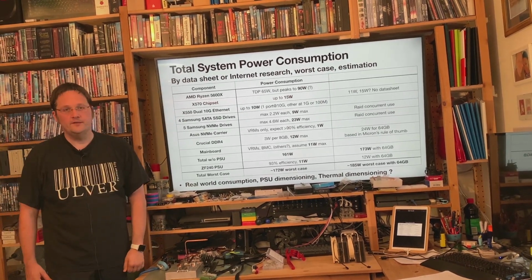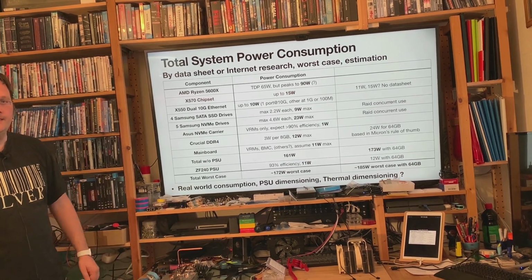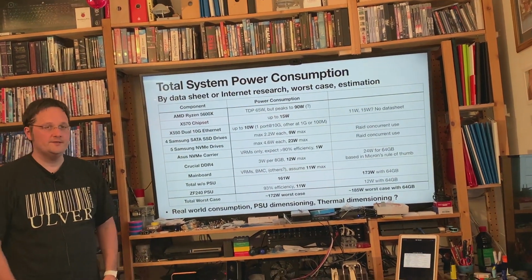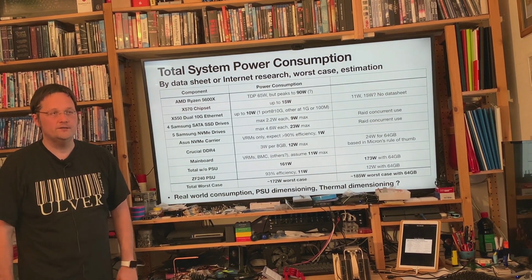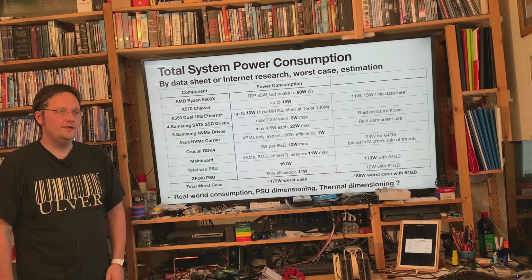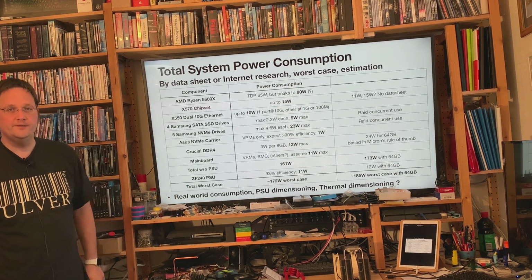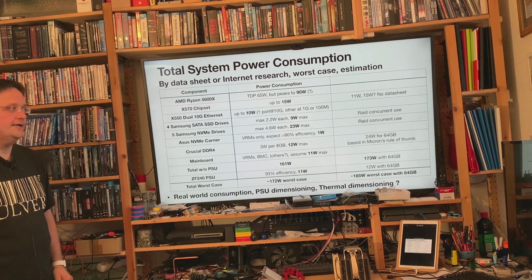The Ethernet, there the datasheet is freely available on the internet. There's a table in the datasheet which says, depending on which speeds the channels are used, the power consumption is given. So I can say that if we are running one channel at 10 gigabit Ethernet and the other one at 100 megabit, the chip will consume in the worst case like 10 watts.